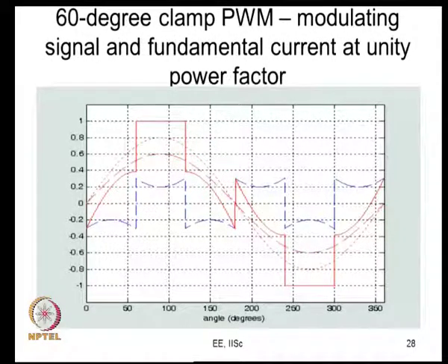Now, look at this unity power factor case. Now, the loss is 0 here, and you would actually have your switching loss going like this. You might actually have it going like this. So, where the switching loss would have actually peaked, here, that you have avoided. So, you have saved a lot of switching energy in this region, and therefore, you have managed to reduce the switching loss.